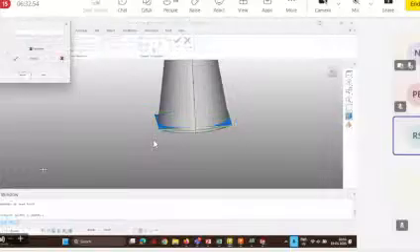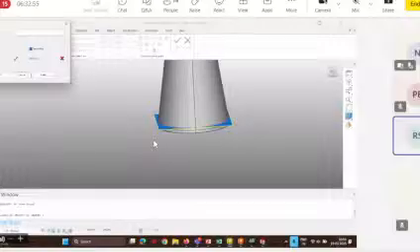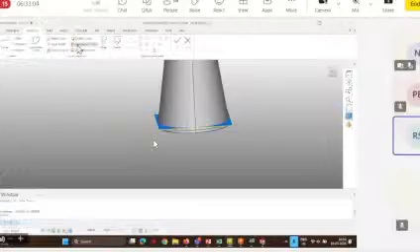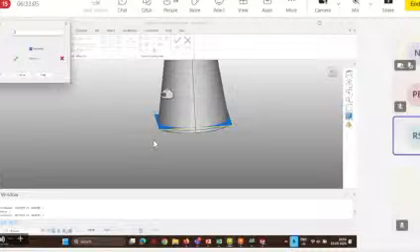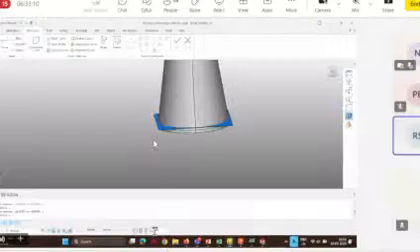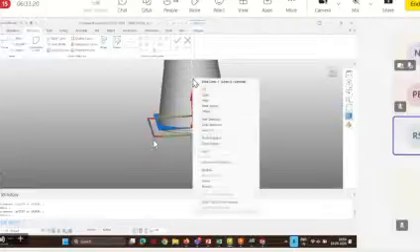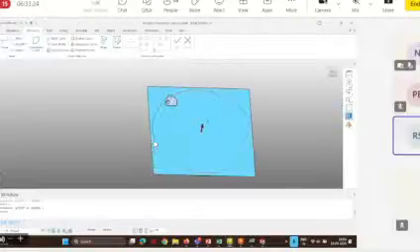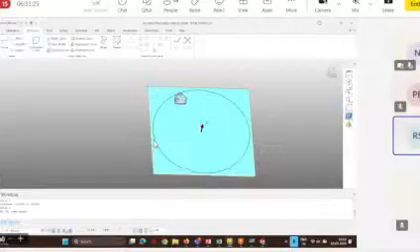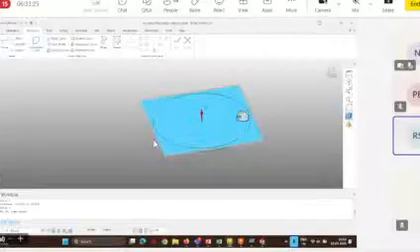Say suppose intersection curve. You can see it's saying enter the offset thickness, and sorry, I selected offset. So it's an intersection curve. First one, this one. The second one is this one. I click OK. So these commands you can actually check in this command window. You can select the option accept or not, the construction method, then accept OK. If I blank this one, you can see this curve has been created. In this way, you can get the commands corresponding to intersection.